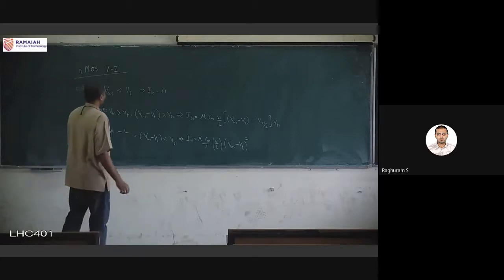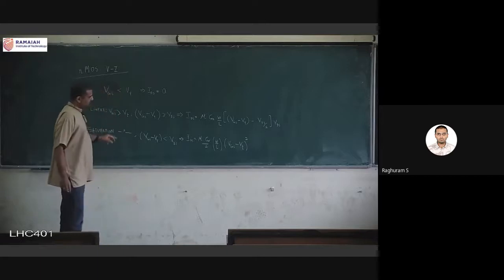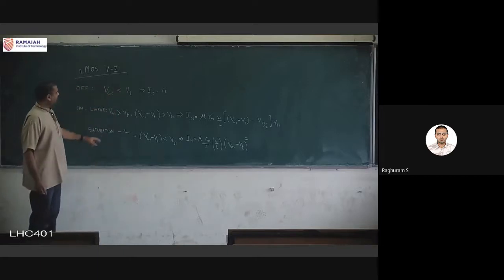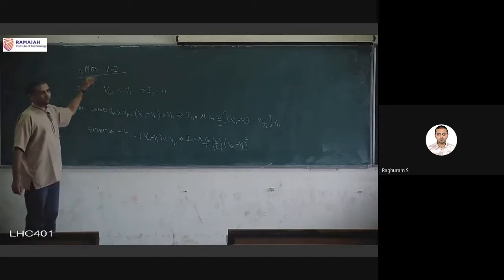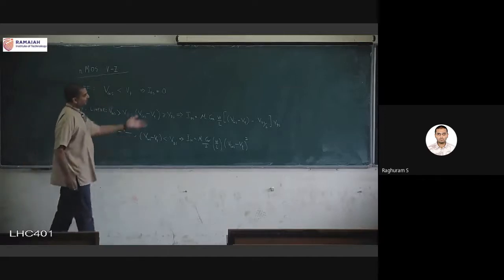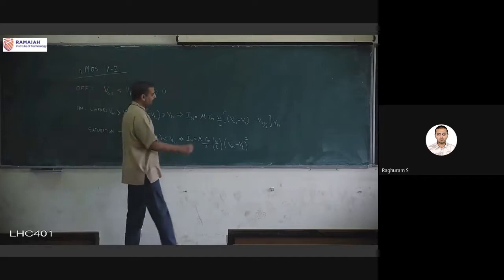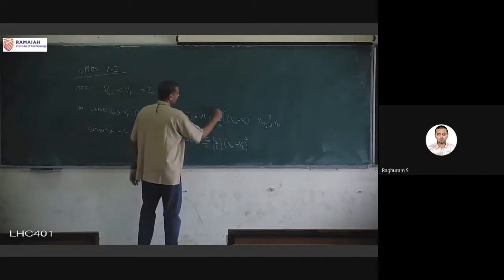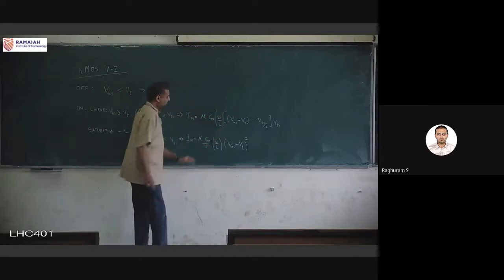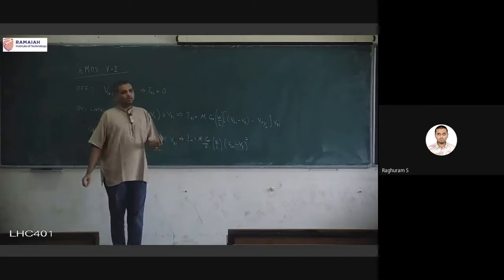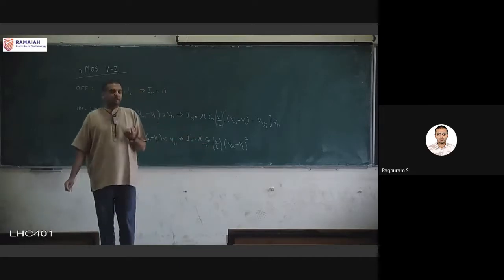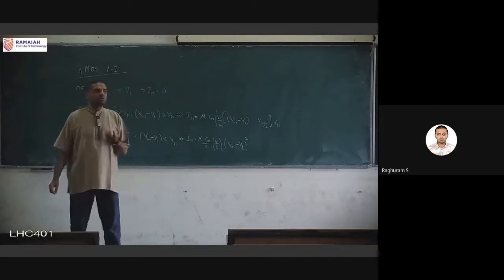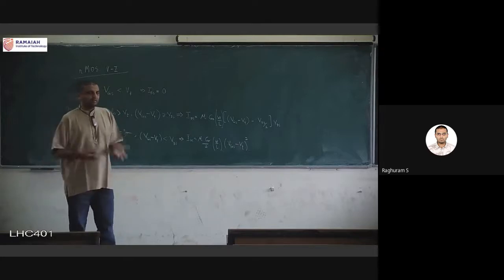And then we discuss the different modes of operation within on itself. This is again for NMOS, and the equation is here. In this whole equation, whatever is within the bracket, the W by L, is our friend. This is the only thing we can use to increase the current. We never want to decrease the current.